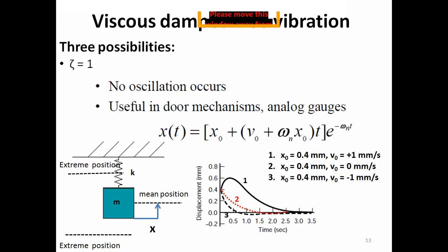In that, we keep the damping as critical, because we want that when the door is opened, the hydraulic mechanism would shut down the door slowly and gradually in the minimum possible time. So we would have damping in that hydraulic mechanism of the door, and we would keep the damping as critical.